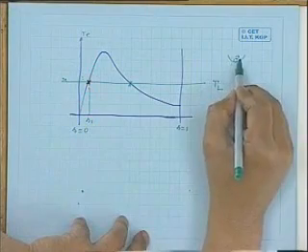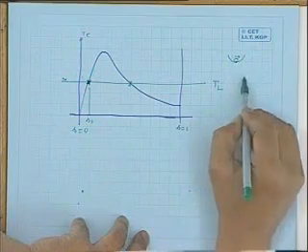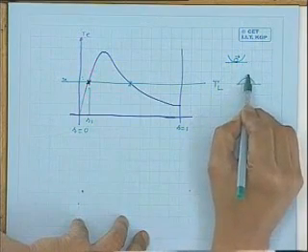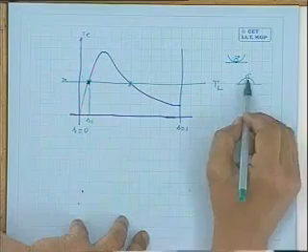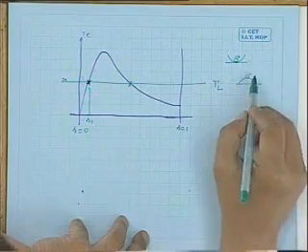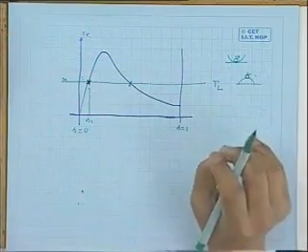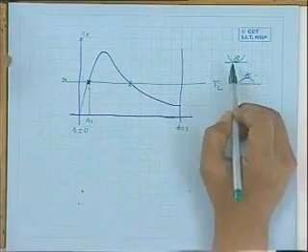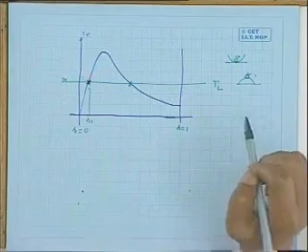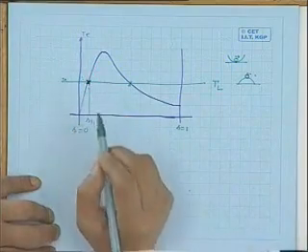For example, a situation like this, you have a bowl and there is a ball. You give a small disturbance and leave your hand. It will oscillate and once again finally settle here. In contrast with this situation, a bowl is here where there is a ball. You give a slight disturbance, on its own it cannot come back. It will roll down to the ground. Are you getting? This is unstable. This is stable, although it is very precariously stable at this point. This will remain stable, critically stable. But this fellow is quite stable. That is, given a slight disturbance, it will on its own come back to the origin.